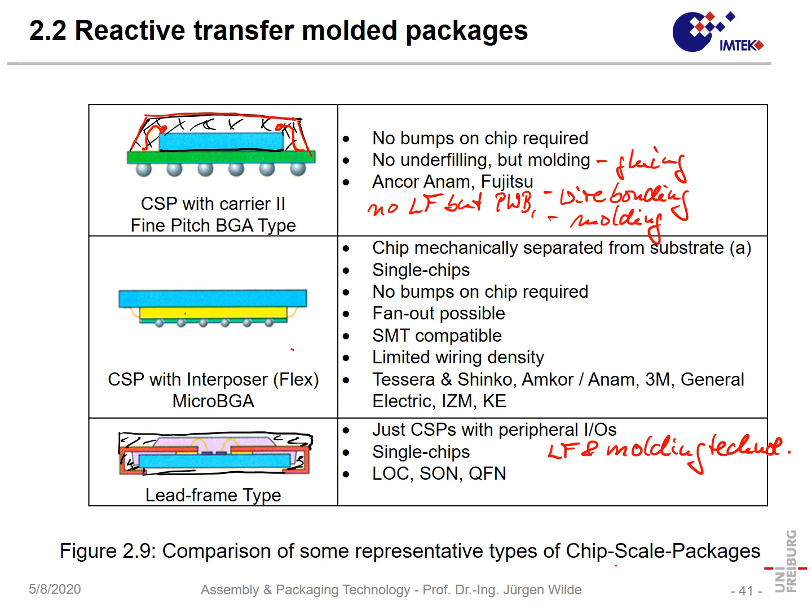Other companies had other ideas. One of the reasons is that you don't want to pay for patents of other companies, so some companies design their own package. For instance, we have the silicon chip here, then we just take a foil which has the balls, and that foil is attached here to the chip.